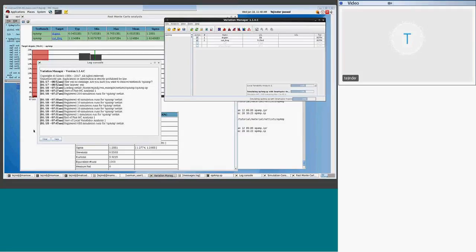So if I want to study local, I could turn off global, right? You can. Yes. Vice versa. But the global is going to affect your local too, right? You can do that, but there is still an impact of the global on the device too. The device sizes and others will all have variation of VT and other things. So you cannot completely isolate that, but you can define it a little bit more intelligently.